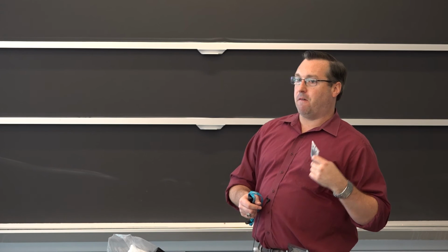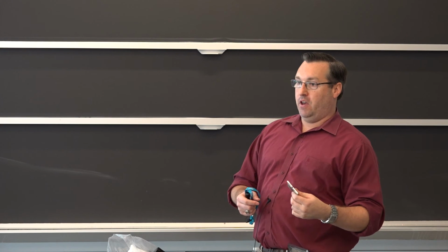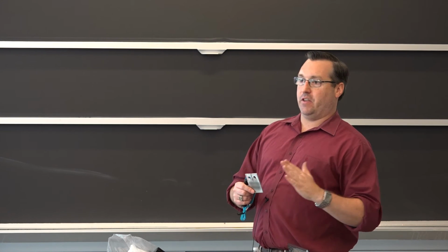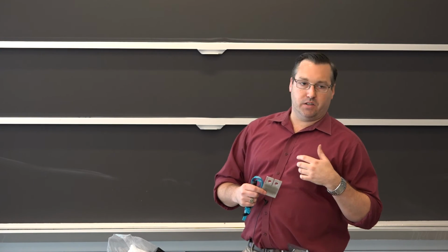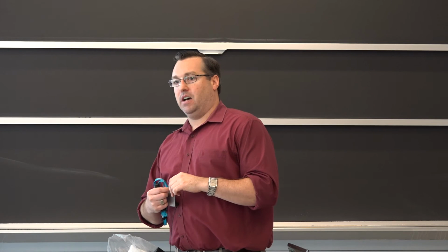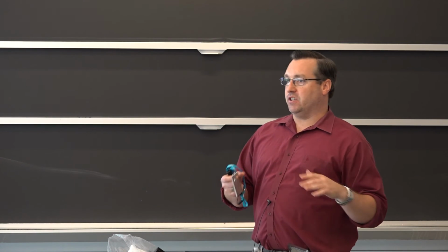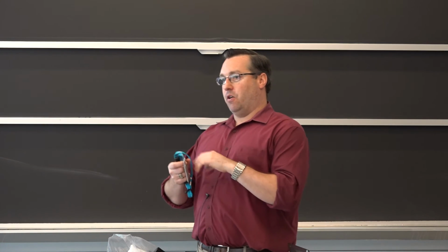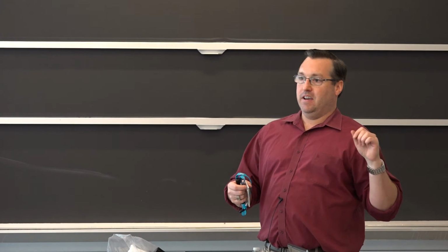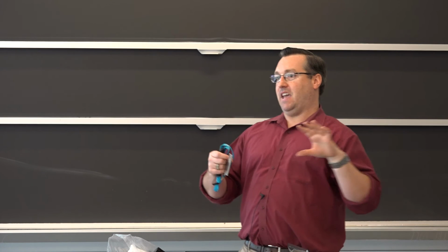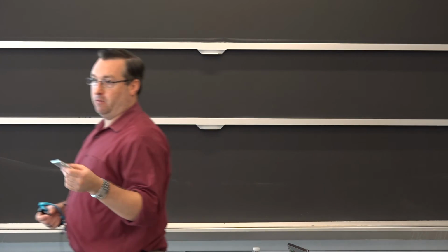When you're talking about fracture mechanics and crack growth, we need to understand the rates at which these things grow. A lot of times you'll design something, and some of the industries say leak before burst. You want to design it so it's not a catastrophic failure, so that you can go in and maintain it before critical fracture occurs. So this would be a CT sample.